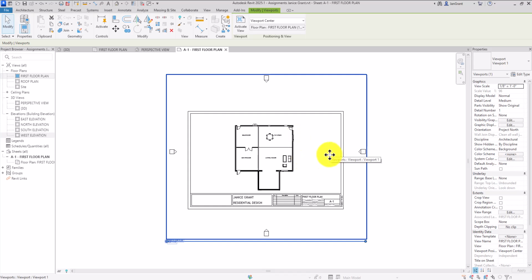The reason we have this huge view is that the elevation markers right here are in this view. And these viewports, see how they're called viewports? Sort of like AutoCAD has a viewport, are reading everything that's in there. So what we want to do in this case is double click. So roll the wheel back.